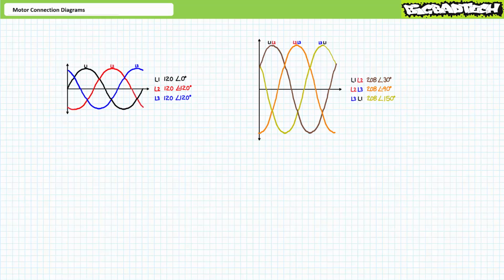First among our tasks is to have a working description of three-phase AC and define the term dual voltage. As a brief overview, three-phase AC is characterized by three sinusoidally oscillated waveforms with equal magnitude and frequency, phase shifted from one another by a relative 120 degrees. A single three-phase AC system, in effect, offers a choice of two voltages: the lower line-to-neutral voltage and the higher line-to-line voltage. Line-to-line voltage is always square root 3, or roughly 1.73 times that of line-to-neutral.